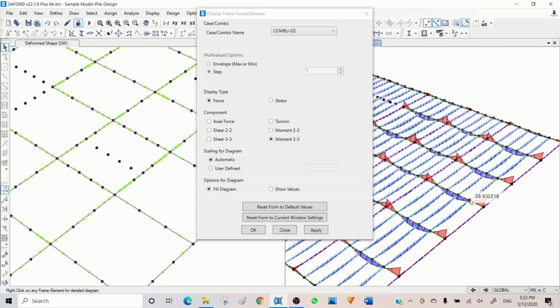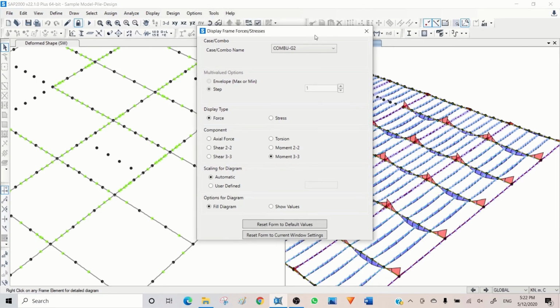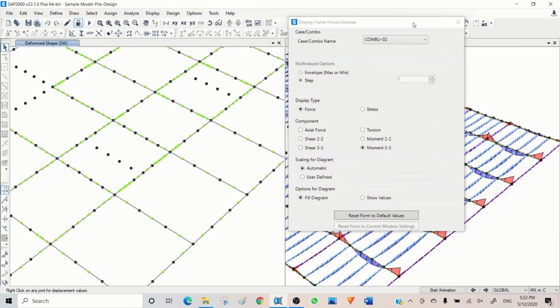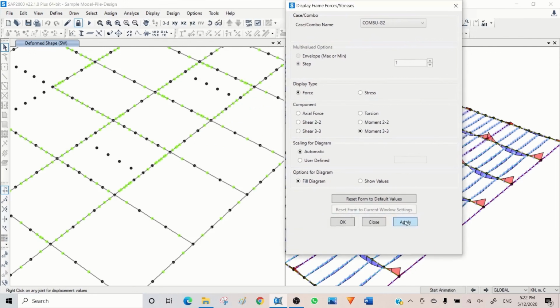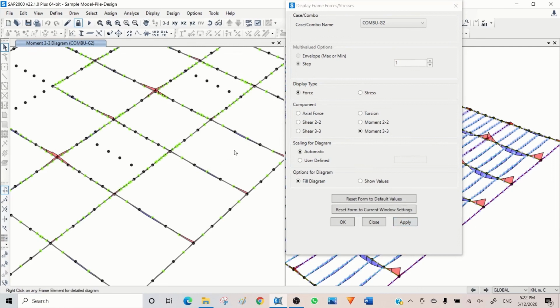This beam, because of using a stronger section and have more stiffness, a slab transferred load to this directly last time. But now you see the moment from 62 changed to 124, here from 5 or 6, maximum 7, changed to 70 kilonewton meter per meter. So what's happening here? Just click here and press apply. So here we had 62, we have 87 now, so the change is not significant. You see it's a bit more, but not that much. Here change, yes, from 24 changed to 33, so this one is just 83.